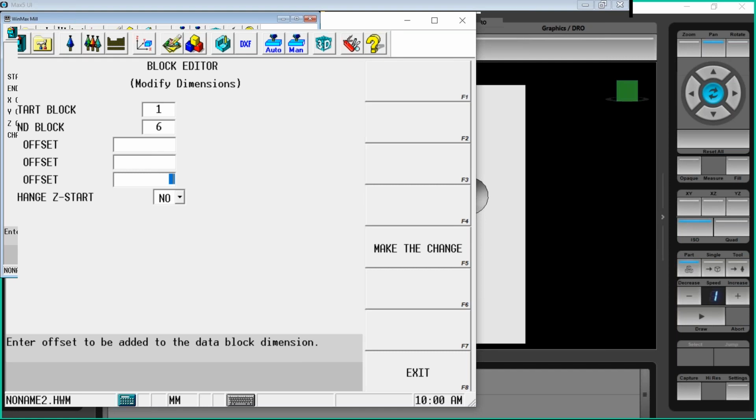Matt asked what type of 3D milling cycles will be available. What we have so far is selecting a single surface or a few surfaces at one time, and the toolpath options are going to be spiral and raster as of this point. So a parallel toolpath, either one-way or two-way zigzag, and you can adjust the angle at which that parallel toolpath goes.